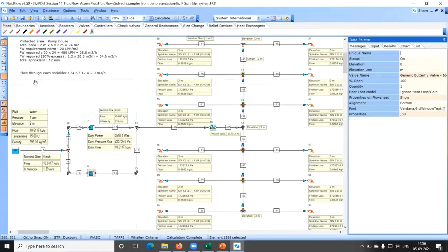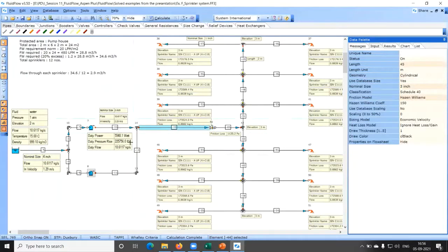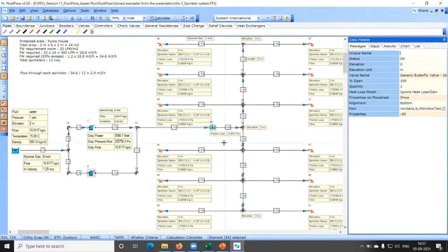And of course, there will be a minimum recycle line, and it will try to maintain some pressure in the pump discharge header. Let us say that pressure is, I'm just putting a number, say 5 bar gauge, right? So just imagine the small jockey pump, 3.5 meter cube per hour, is working. This deluge valve is closed, and the system is able to generate a pressure of 5 bar gauge. Now suddenly there is fire in this pump house. Then the signal from F&G will go to this deluge valve, right?